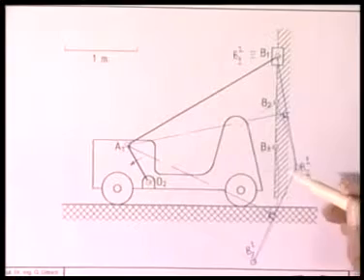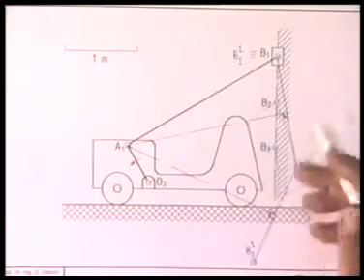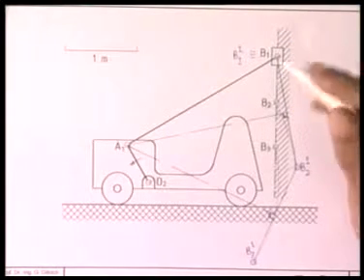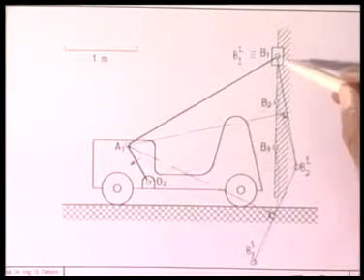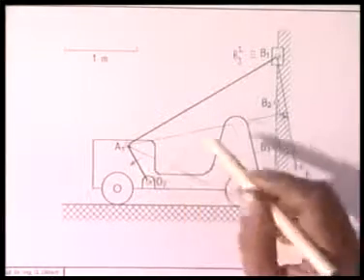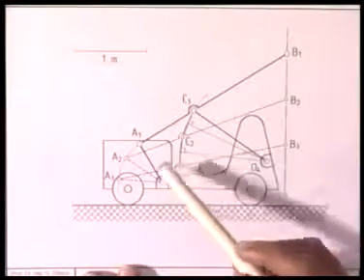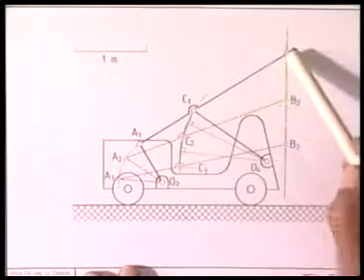In the next stage, we will get to a 4-bar linkage such that I can remove the slider, and this coupler point B1 will automatically pass through B1, B2, and B3 when that 4-bar linkage is moved. But that is the second stage of the synthesis. So in the first stage, we have obtained this O2 A1 B1.